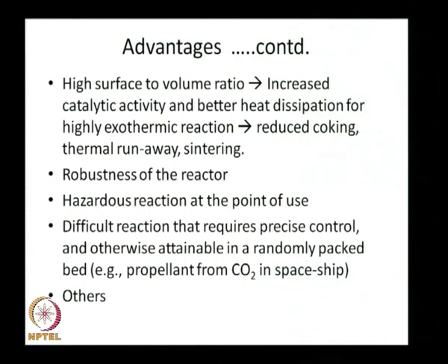So, you want reduced coking, reduced thermal runaway, reduced sintering, and for this purpose, you can have a structured catalyst, that means channels whose dimensions are all uniform everywhere.